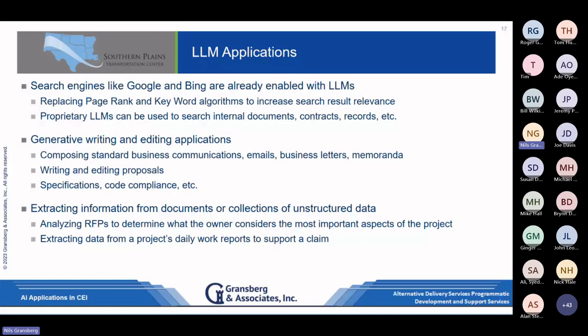Well, we looked at the schedule, and it turns out the schedule didn't have a critical path. They had hand-inputted one of the numbers wrong, one of the start or finish dates. So after about 2 months, the critical path died, disappeared, and showed up at the end. But by using this to rebuild that schedule and do those extracts, we were able to come back to our client and say, guess what? They don't have a claim, because if there's no critical path, there's no impact to the critical path. And they're like, there's no critical path? And I'm like, yep. Wow. So they were able to negotiate that one and get it back going.